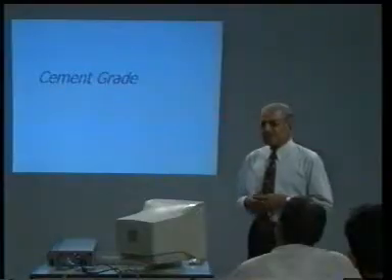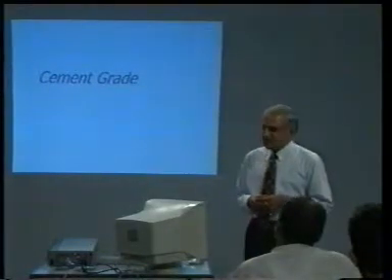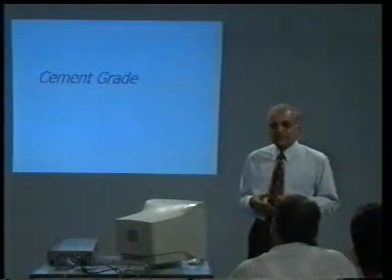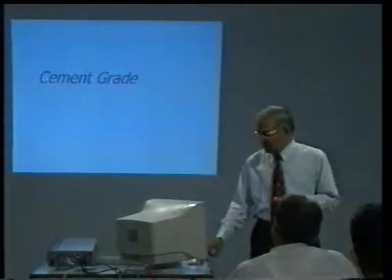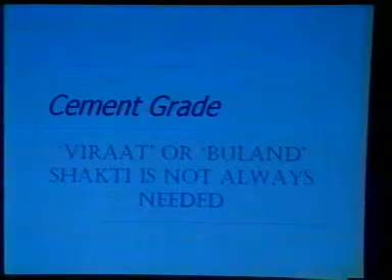A word about the cement grade. Cement grade, gentlemen, people are now publicizing. The big factories are talking of Virat Shakti and Buland Shakti. You tell me, what is the purpose of providing 53 grade cement in a masonry structure where the strength of the brick is only 70 kg per centimeter square?